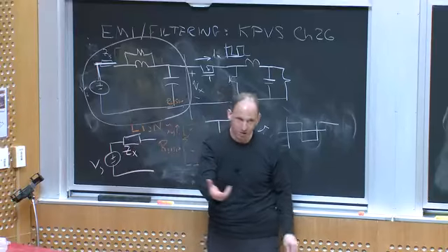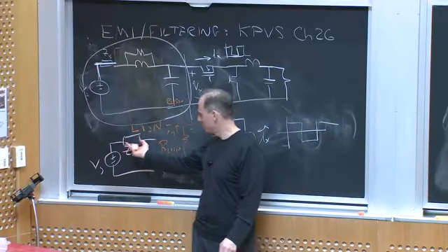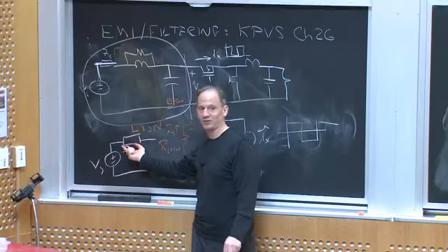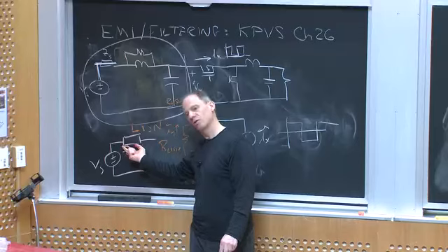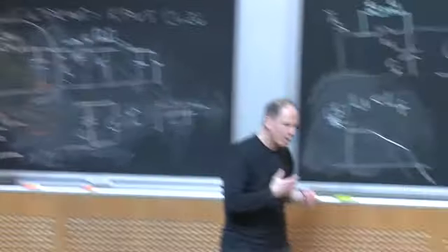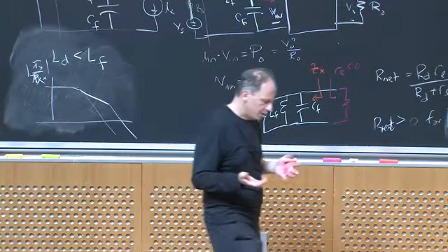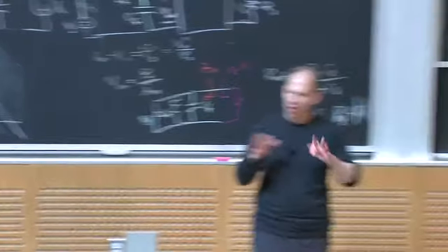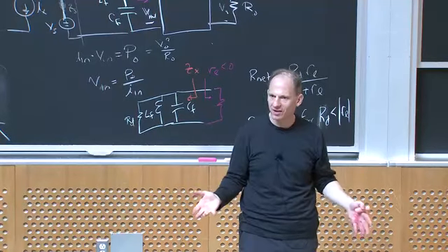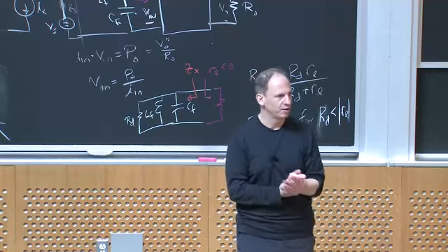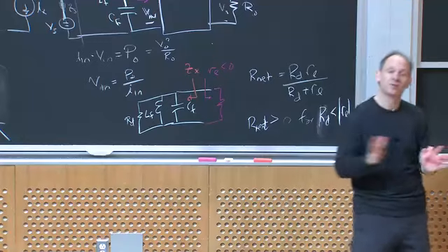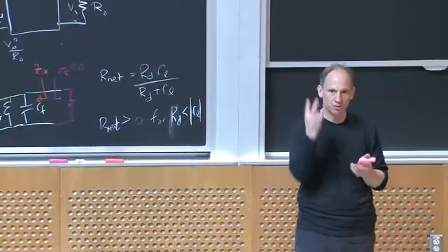And my assumption in designing the converter and controller was that Zs was 0, or Zx was 0. But Zx isn't 0 once I've designed my filter, right? How close do I need to make it towards 0? Well, what I would like is the case where all of the models that I use to derive my converter, control, transfer function, all that stuff, is valid and not affected by the filter I design later. And a sufficient, not necessary, condition to doing that is two things.